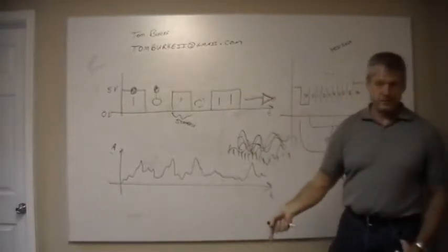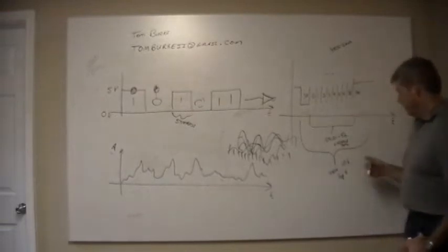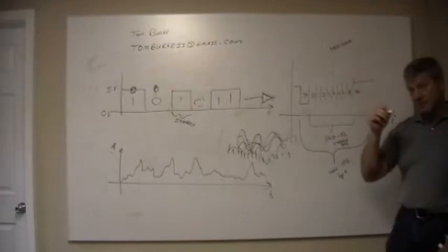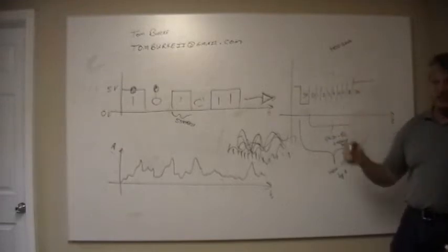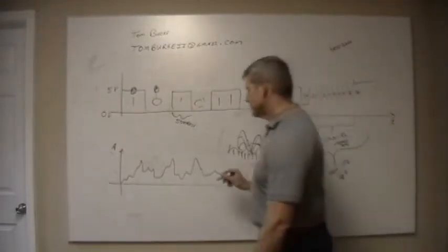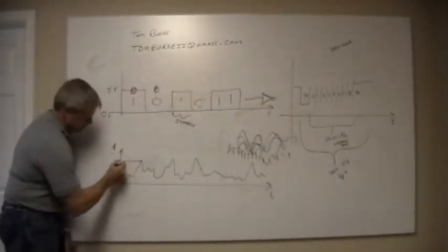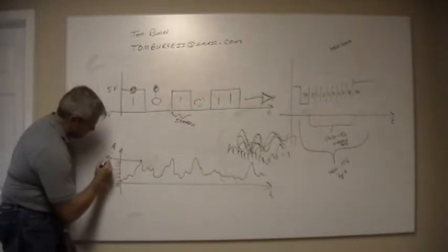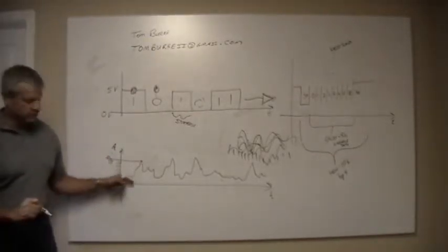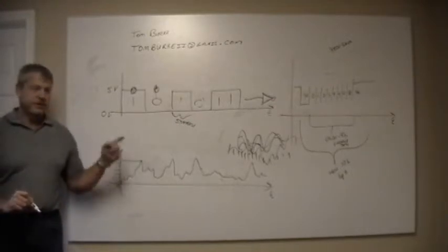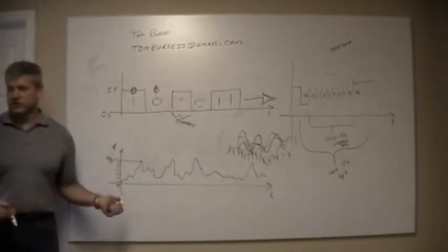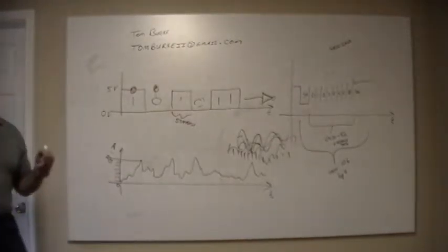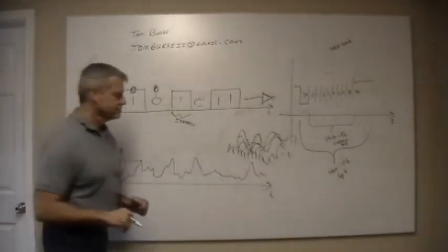What we call an analog to digital converter, we won't get into it too much, but our microcontrollers generally have one that's at least 8 bits, which means 256 different states. So it can count from 0 to 255 different levels in there. But that's a lie, because usually the bottom 1 or 2 bits are trash. So it's more like 128 or 64 levels of data.